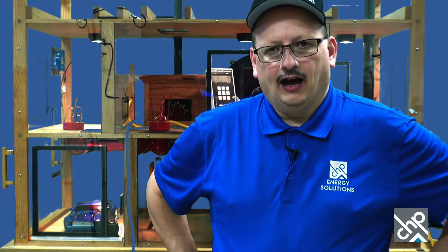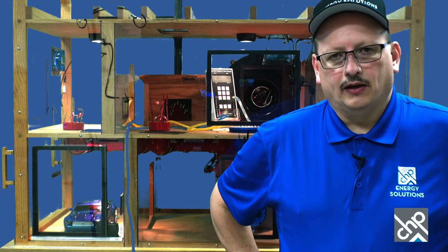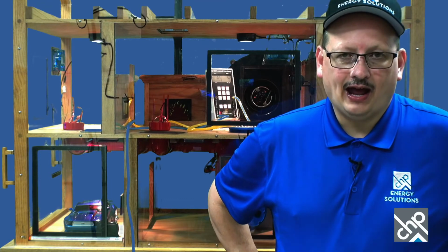This is like a door closure test. And you typically do this when you do your CAZ test and combustion safety, maybe along with the dominant duct leak test. But you're just wanting to know that the air can get from that room back out to the main body of the house, even when the door's closed. And again, it all goes back to all those main things we said: health and safety, durability, comfort and efficiency. All those things get affected just by closing the door.